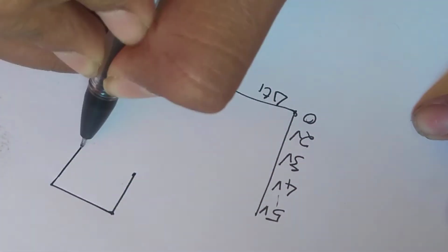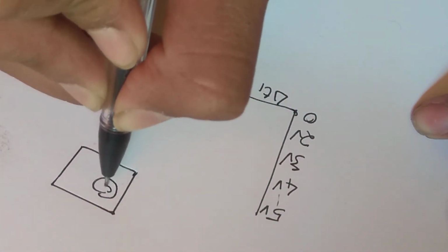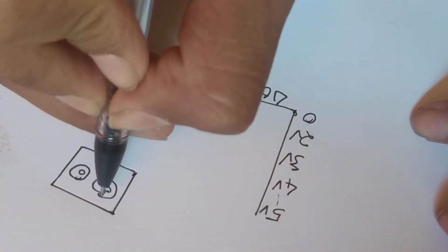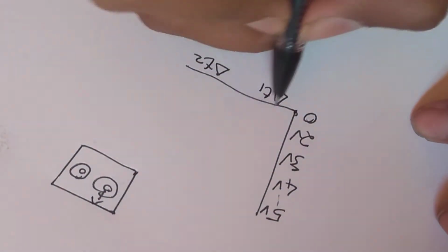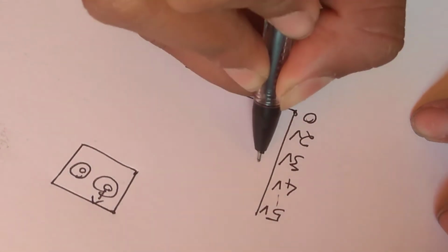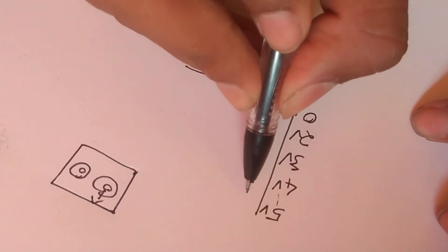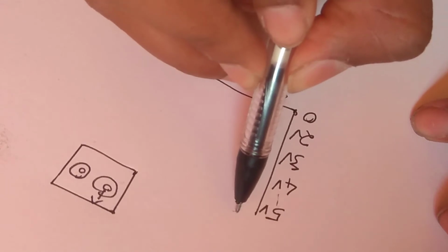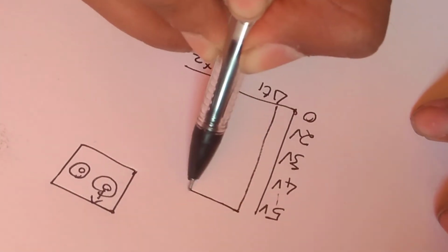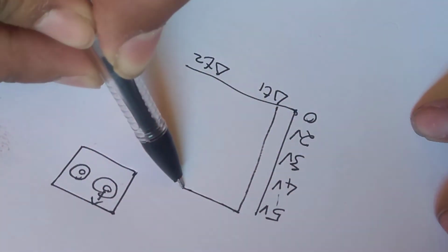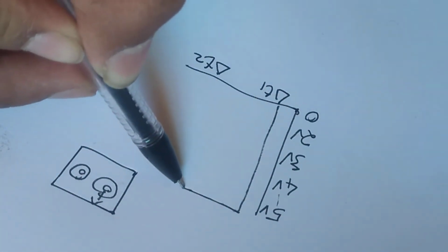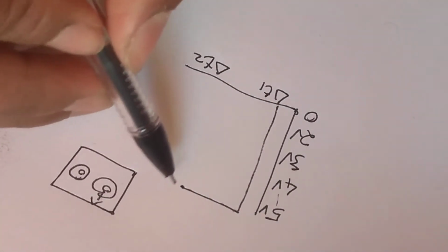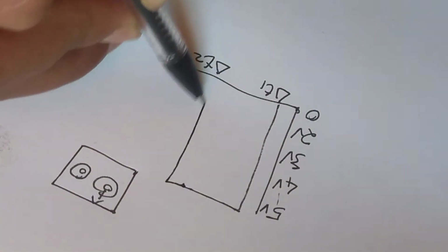Now, imagine this is our remote. It has sticks. Now, if the throttle is raised high, meaning at the front, the signal pulse will change. It will rise to 5 volts, or if it's full throttle the voltage will be high and stay constant for a few milliseconds, because this whole thing is counted in microsecond pulses, and then it will fall down.